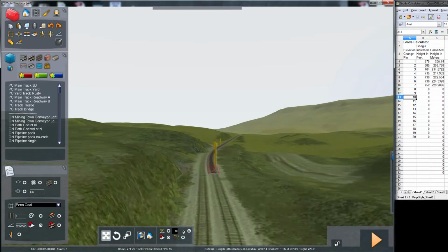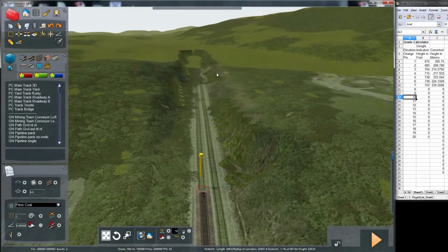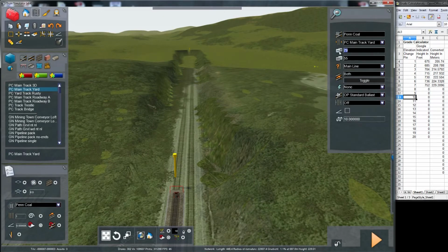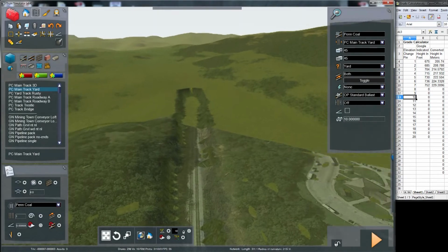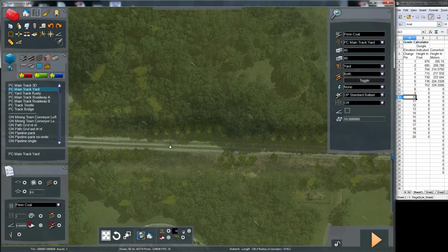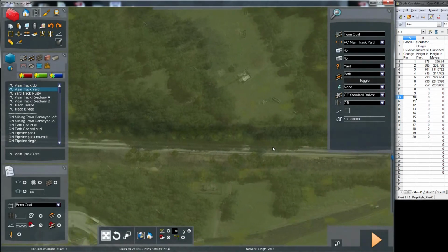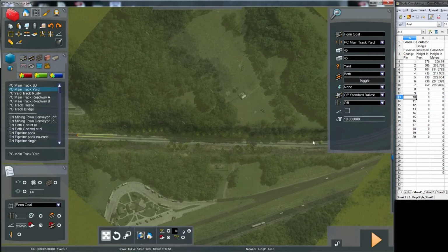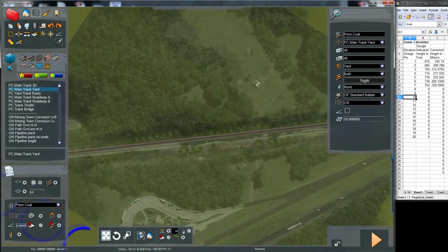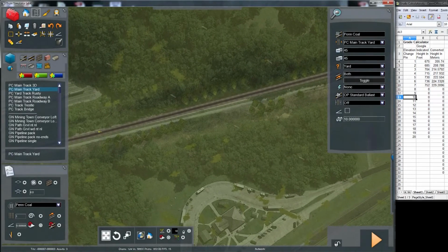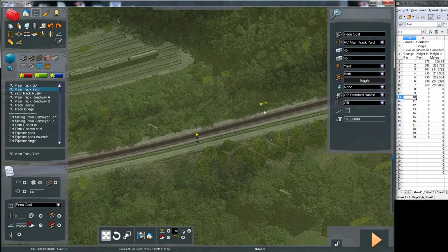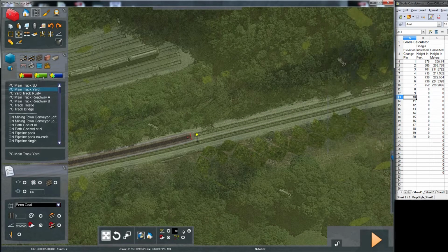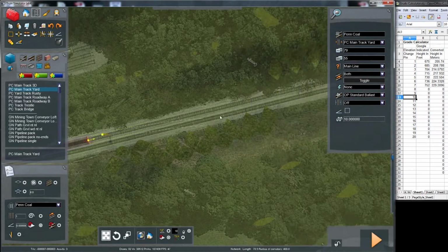And we'll set up. And I don't know how that happened. But at some point when I was quickly snapping through doing the track, it was not tangent. And that's why I guess I had pulled it over to meet that. So we're going to need to do a little trim job here, which we can do with the split tool, and we'll split it back to about right there, and we'll try laying it again and see what it looks like. I'm not going to make any adjustments. I'm just going to see how it looks if we pull it up there.